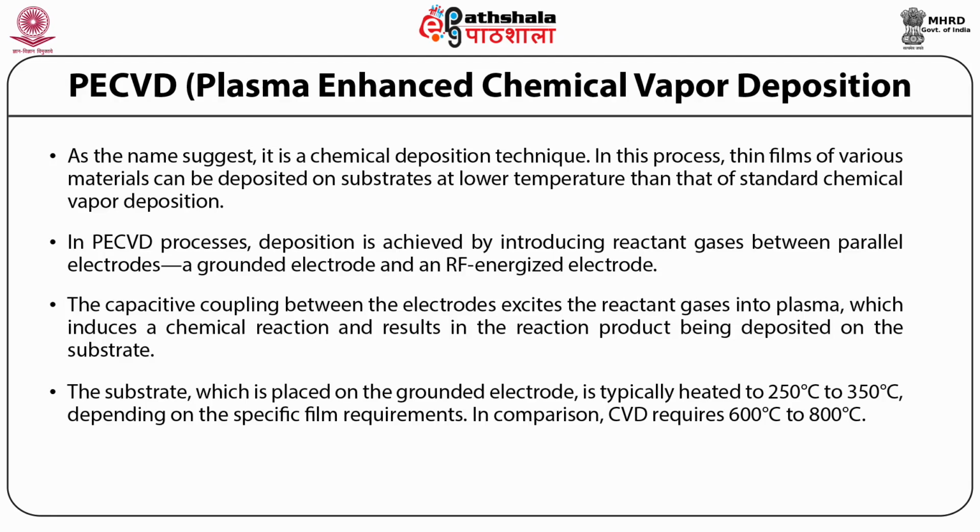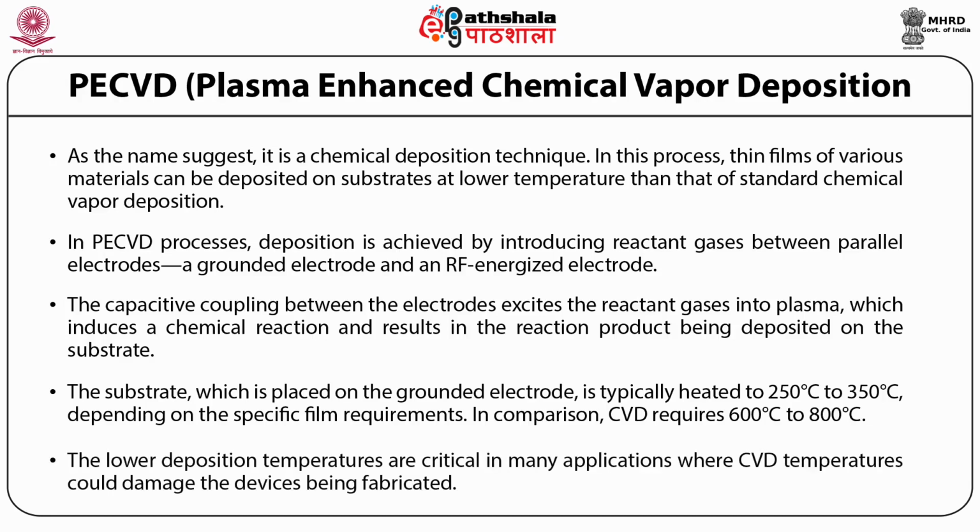specific film requirements. In comparison, CVD technique requires 600 to 800 degrees Celsius. The lower deposition temperatures are critical in many applications where CVD temperatures could damage the devices being fabricated.